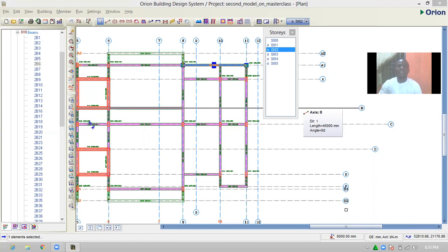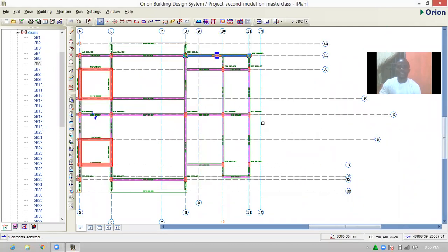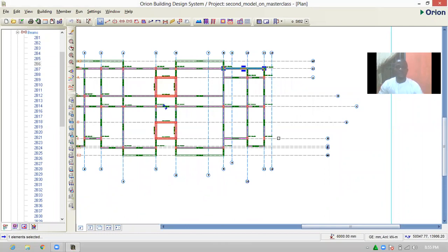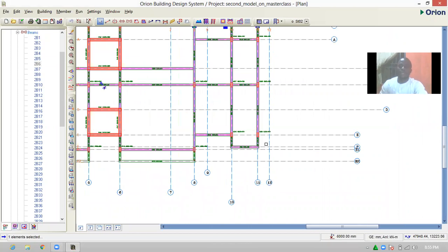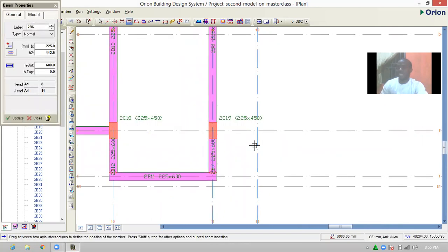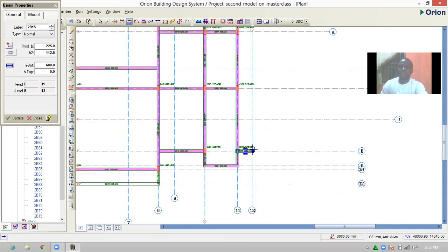Okay, how to extend the beams for the cantilever. If you understand, let's say this is in this floor, we do not have a cantilever here. Because of this question, I'm going to add a cantilever beam here. You just select your normal beam. You select your beam. This is the axis we offsetted. We started it from story 3, this part from story 3. So I'm going to put it up here, and I'm going to extend this.